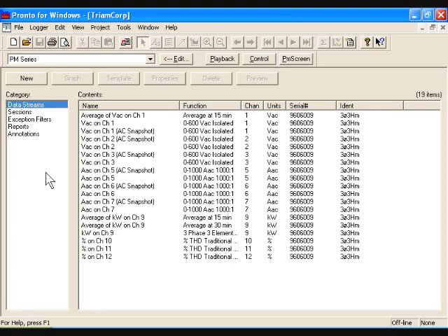These are 3 models of a PM7000 that will be released in the fall of 2005 that include a feature called Waveform Capture. This instrument is going to be a very powerful instrument, and typically most instruments nowadays have memory on board, like we have 1 meg on our 3000 and 2000. The PM6000 had 4 meg. Some people have a few meg more than that, but the PM7000 is going to have 160 meg of memory in it, and 32 meg of memory is going to be assigned to waveform capture.